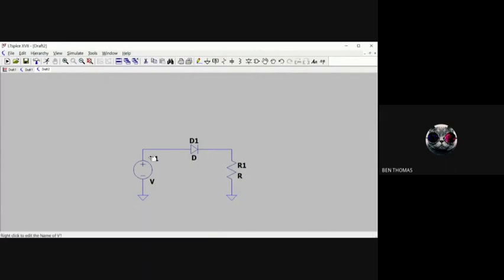So let me just imagine a scenario where I want to add a sine voltage source to the circuit. For that, let me hover over this voltage source, and when it changes to this hand symbol, right click on that, and a pop-up like this comes up. To change it to a sine source, like an alternating current source, you can click on this advanced option.